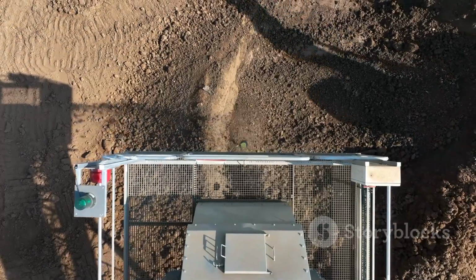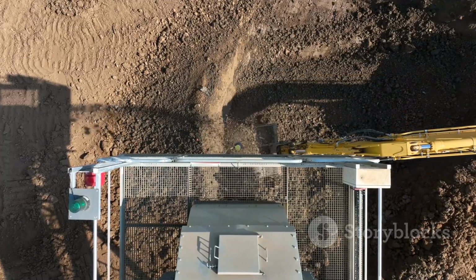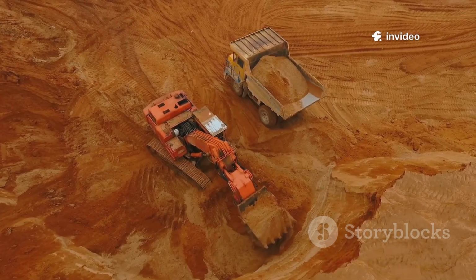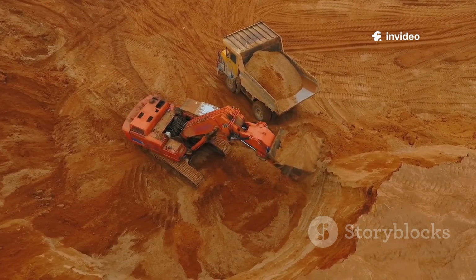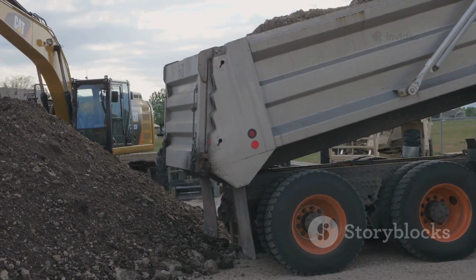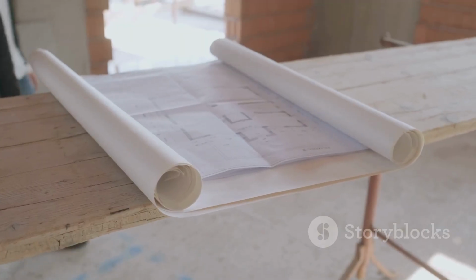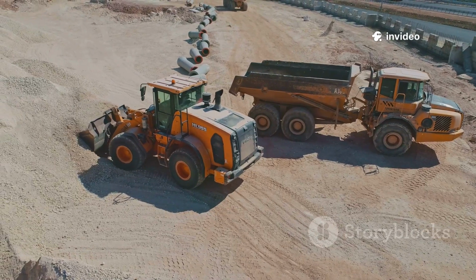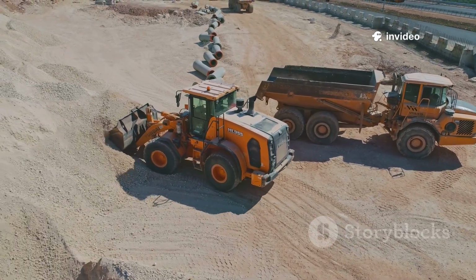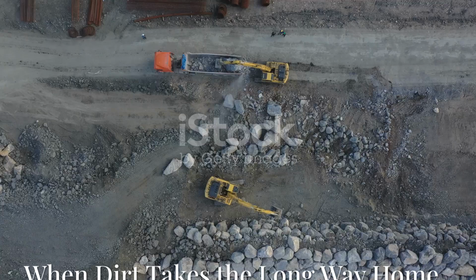The goal is to maximize the amount of dirt moved under free haul, keeping costs low. The diagram helps pair cuts and fills that are close together, making the most of this free movement. Every cubic yard moved within free haul is a win for the budget. This is where the diagram becomes a strategic tool, not just a chart. Efficient earth moving starts with maximizing free haul. That's the bread and butter of every earthwork plan.